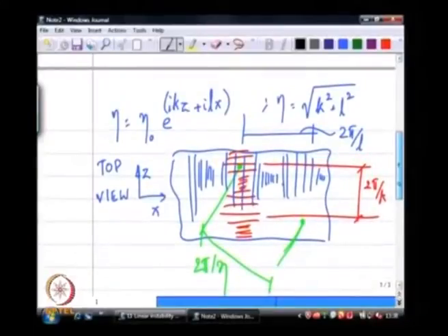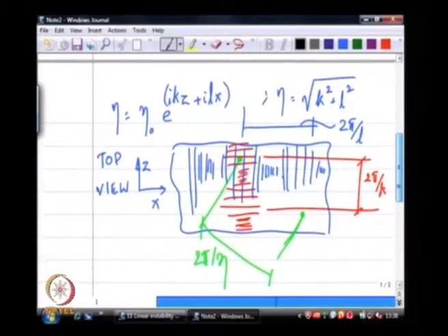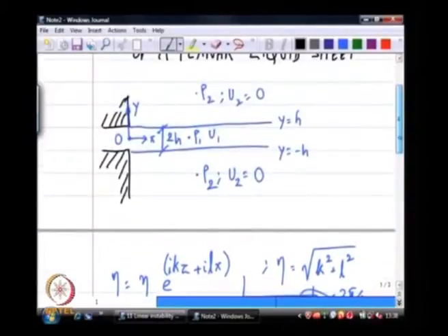Okay. So, it is sufficient for me to consider the k equal to 0 mode, because k equal to 0 or L being finite is the mode where we only consider instability along the flow direction, and that is what he referred to as two dimensional modes. So, in order for me to show you both k and L, notice how I had to draw a plan view alongside the elevation view.